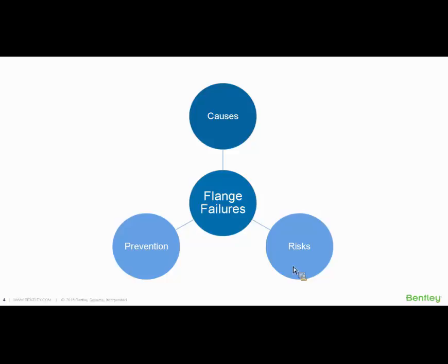So basically, a bolted flange system is a method to connect piping systems, vessels, heat exchangers, valves, and equipment together for a piping system to be complete and pressurized. The advantage of bolted flanges is that they provide access for cleaning, inspection, and maintenance of piping systems when required. A flange joint has two flanges with a gasket in between them for sealing, and tightening the bolts.